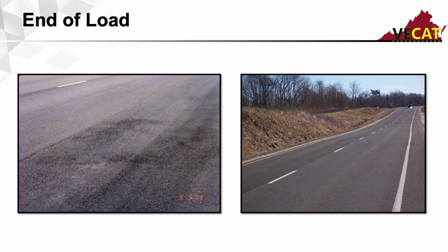So as you dump the material into the paver, we're not remixing it with a transfer vehicle. As that material goes through the paver and goes out behind the screed, it's very coarse. What will happen in time is those areas will be the first ones to fail. They'll crack and they'll pothole.